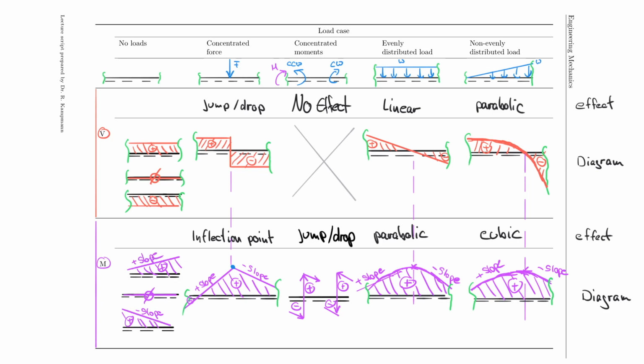And that therefore shows us how these cases relate to each other, because remember, the very important thing that we learned before is that from the shear force to the moment we really integrate, or we actually took the derivative to arrive at the shear force from the moment. But we also did this for the load case, so we could have done this integration here, or we could have taken the derivative in the other direction.